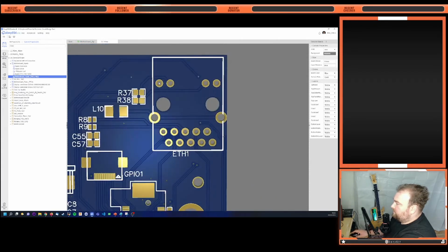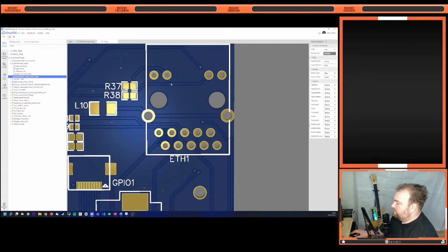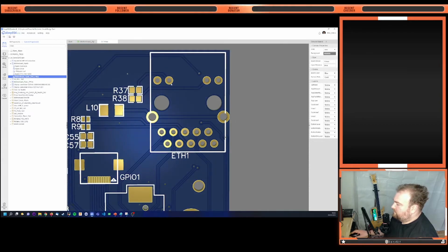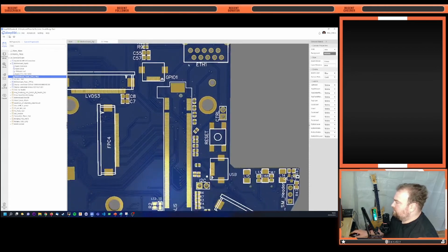These are the pins for the lights you normally see in these kinds of ETH protocols. They are not so important, but I have mismatched them. They should be connected to ground, and I've connected them to 3.3 volts. So all my lights are never shown. This is a little bit bad.